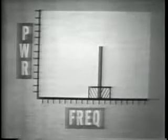Now, we have seen that identical intelligence is present in each of the sidebands. Since either sideband carries the same intelligence, transmitting both sidebands is a waste of frequency space. Since the carrier and one of the sidebands are not required for transmission, why don't we eliminate them and use their power to boost the remaining sideband? Well, let's see what would happen.